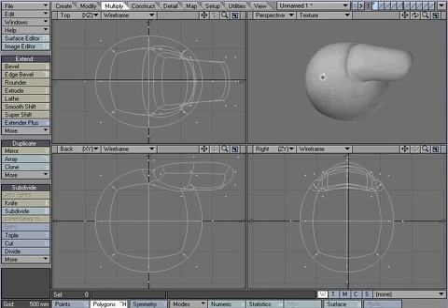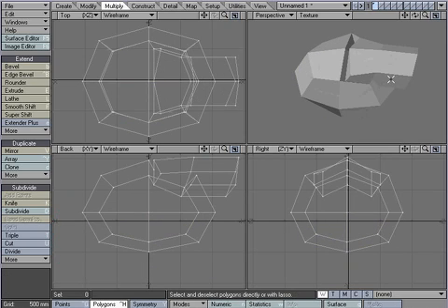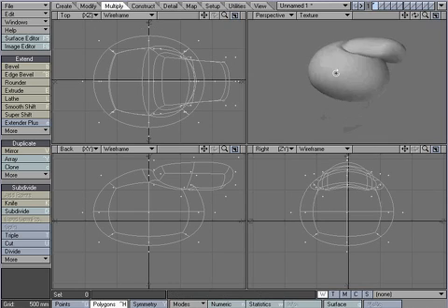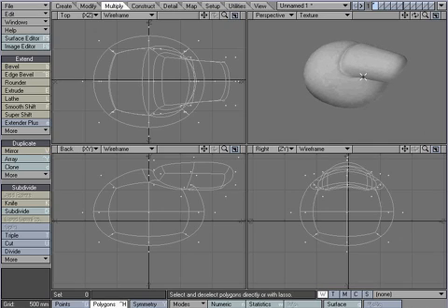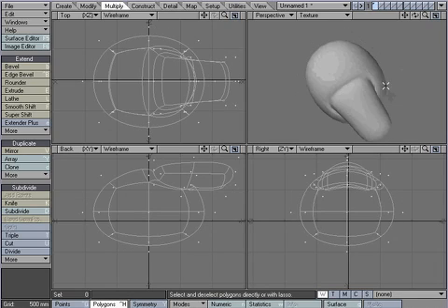Okay. Now, what I did to turn on subpatches was I used the tab key. Just by hitting the tab key, I can go from a low poly polygonal object to a high poly subpatch or subdivisional surface object. This is really important now that games are becoming more and more high poly mixed with low poly. So you have a game like Doom 3 where you use a low poly object for in-game, but it's using the normal displacement information of a high poly object.